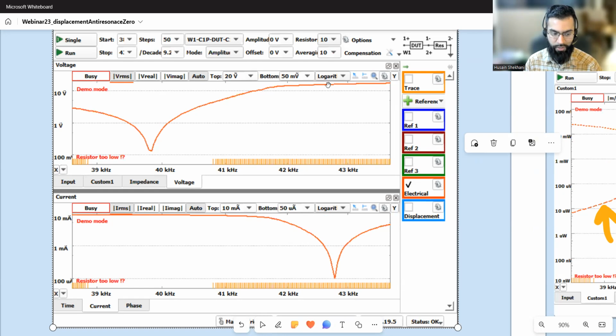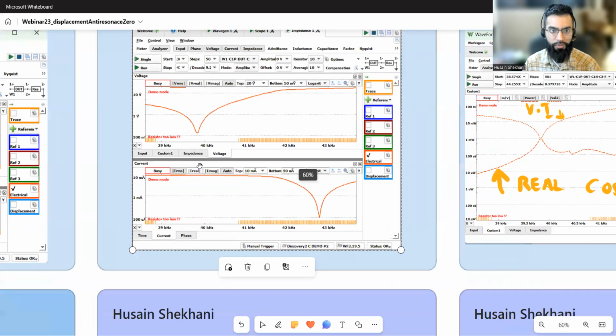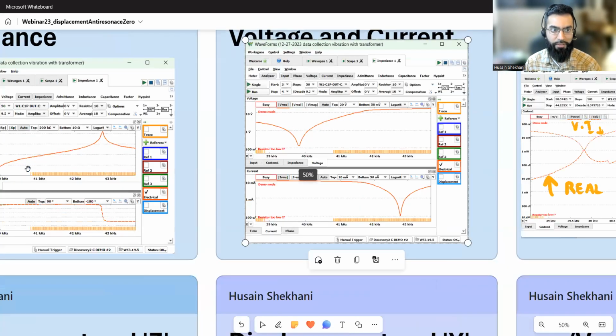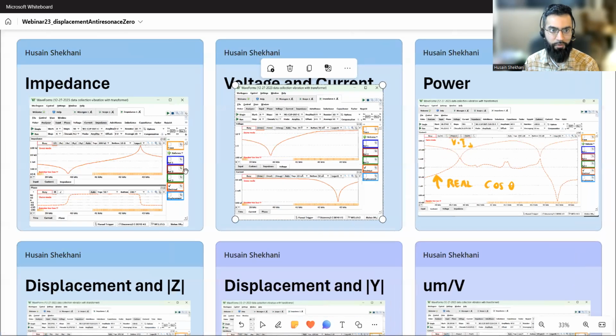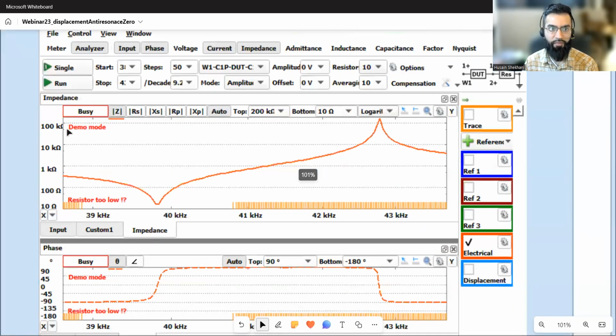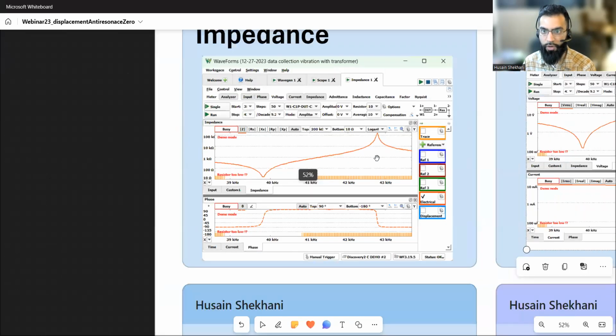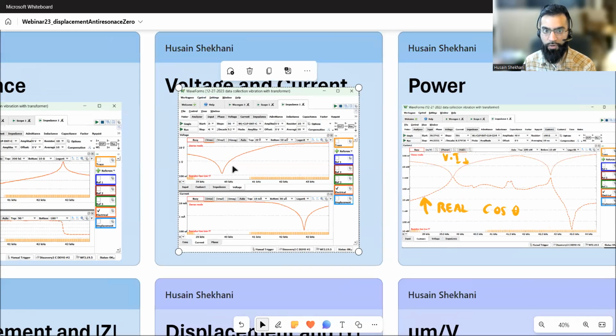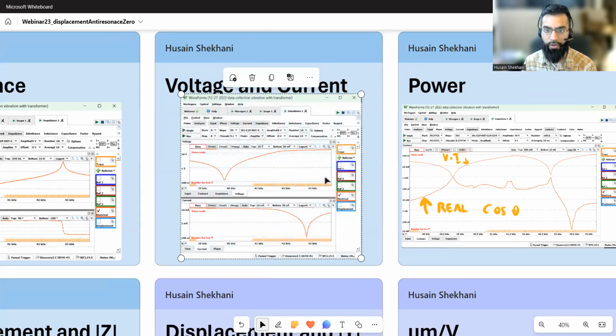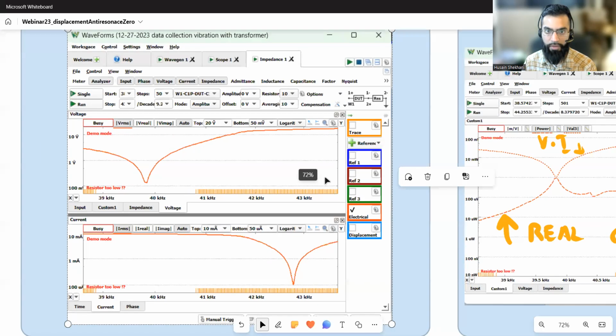Let's assume that the output impedance is actually 1300 ohms, like the data sheet of the transformer was saying. In that case, since we have almost 100 kilo ohms, after you get past a certain point, you have a very large load. So if you have a very large load, you're not going to be changing your load impedance practically with regards to the transformer. So it's constant.